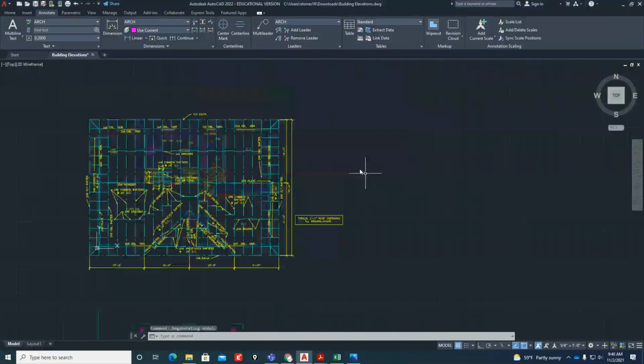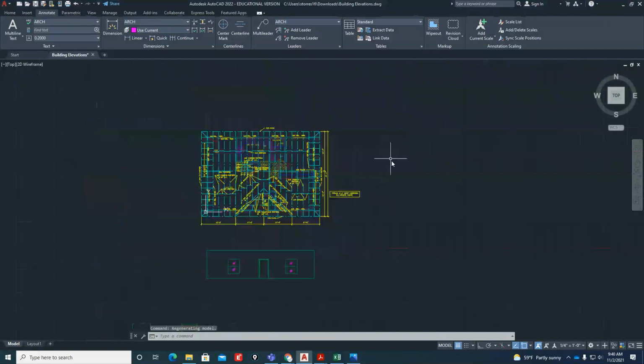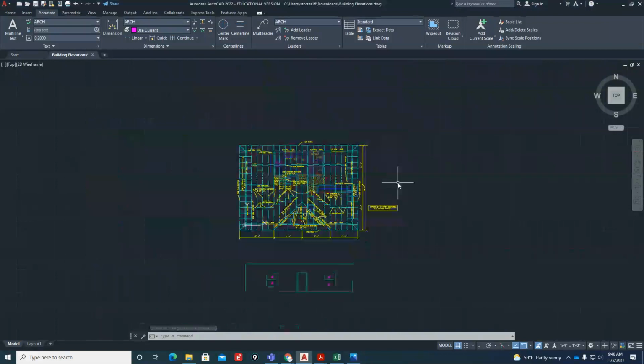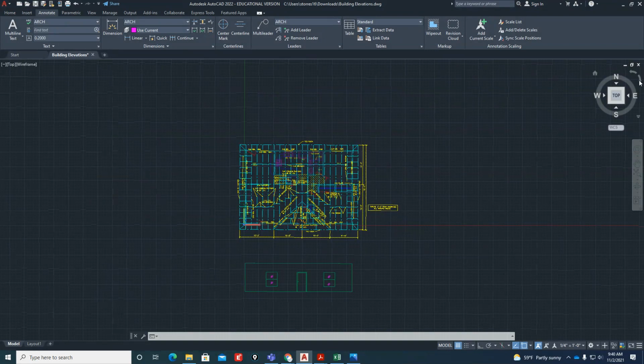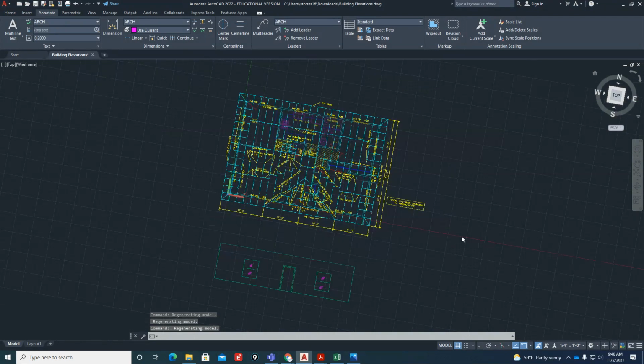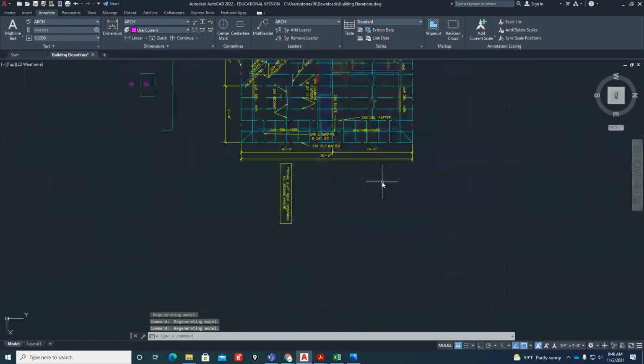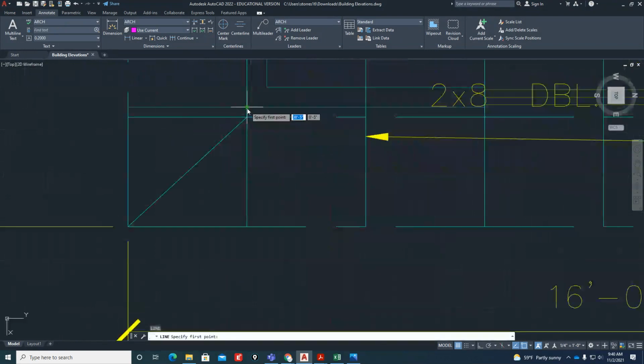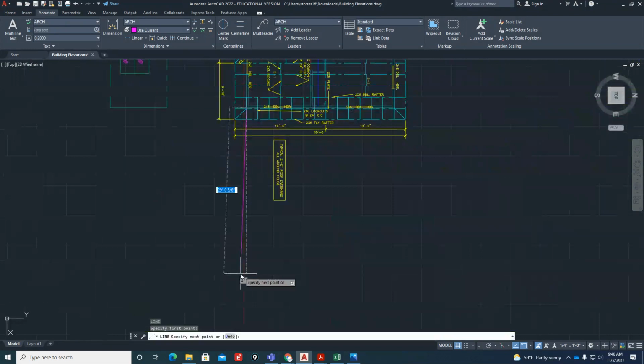So to get that roof, I need to work off of the other views. Which is why I like using the roof framing plan. Because what I'm going to do is draw the right side view over here. No reason why I'm using the right side, I just would rather use the right side. So I'm just going to simply rotate the view. And I like to draw in my oriented X and Y like this, so that from here, I can start drawing up the right side view.